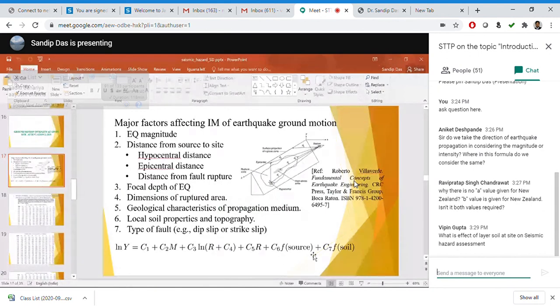Now you see, this soil is there in the attenuation model itself. So that is a crude thing. You can separate this into two parts. In one part, you will find an attenuation model that will give you the shaking at the bedrock. In the next stage, considering whatever soil layer is there, you do a rigorous analysis of wave propagation through the soil using some software like Shake or maybe Plaxis, or some other relevant software.